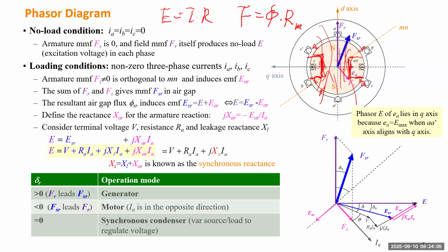So if the reluctance is bigger, the phi will be smaller for the same magnetomotive force. If you have a fully magnetic material, the Rm can be small, and phi can be big. But for the air gap, the magnetic reluctance Rm can be big and phi will be small.